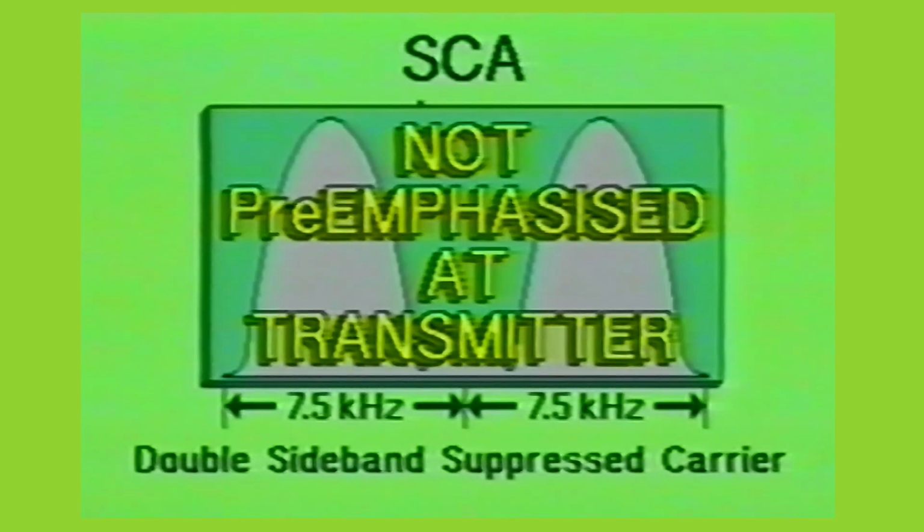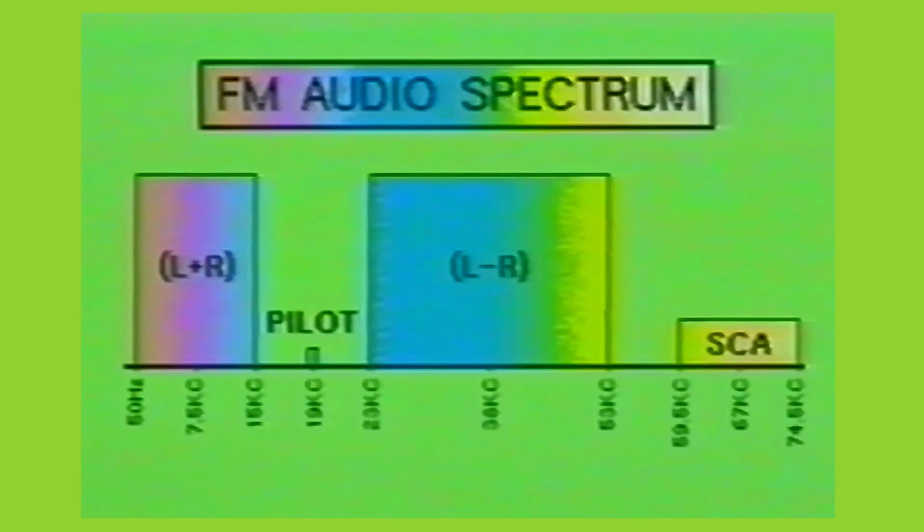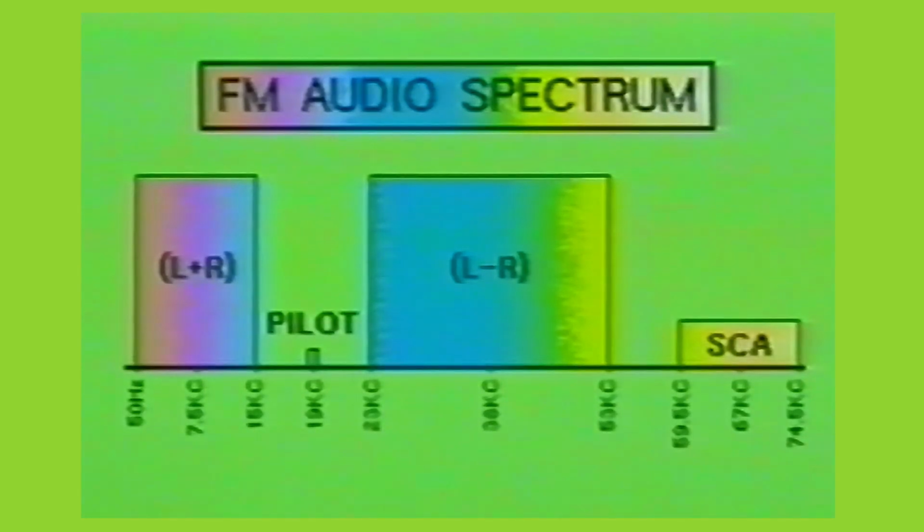The SCA information may be located anywhere between 20 and 75 kHz on the audio frequency spectrum or baseband of the main FM carrier with respect to bandwidth already in use. If the FM station is broadcasting stereo multiplex, the SCA signal will be placed after the multiplex information, usually at 53 to 75 kHz, with the suppressed carrier having a frequency of 67 kHz. Sometimes a second SCA signal is centered at 92 kHz in areas where FM stations are far enough apart on the FM band not to cause interference with surrounding radio equipment.